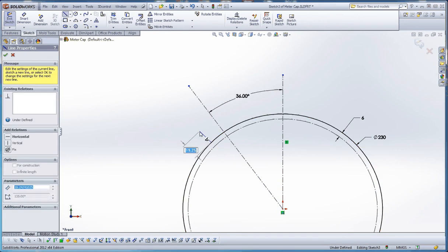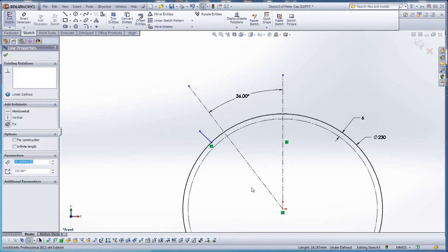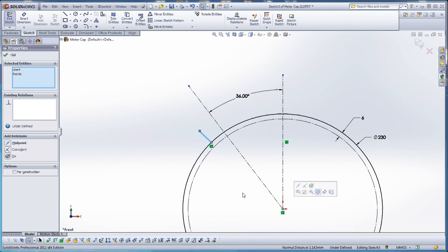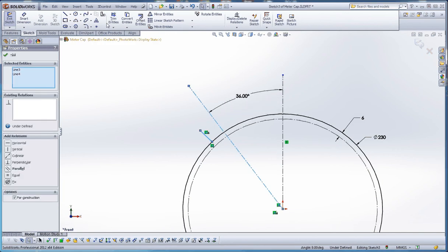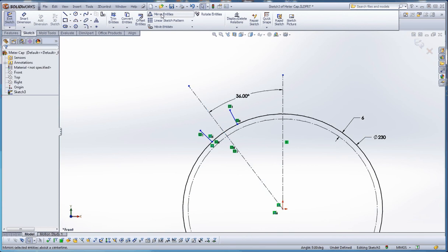I'm just going to draw a line out here. We're going to make this line coincident with the center down here. We demonstrated this in class on Tuesday. And now we're going to take this line and mirror it on that center line. So if we just pick these 2 elements and go up here to mirror entities, nothing additional needs to be done. It remembers those selections.